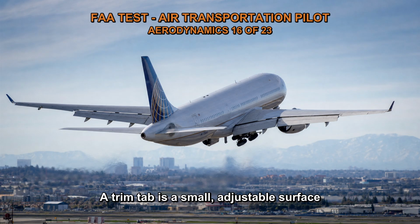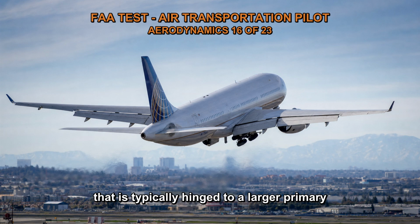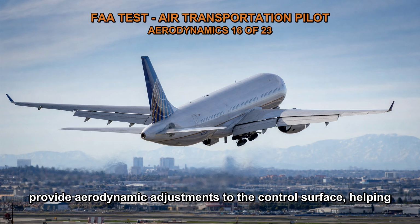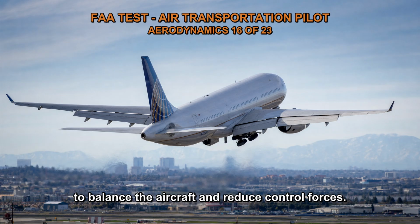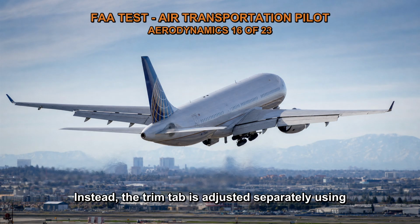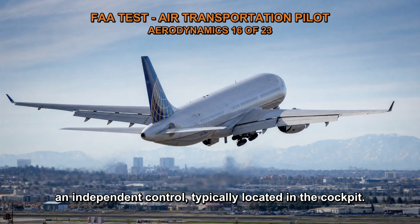A trim tab is a small, adjustable surface that is typically hinged to a larger primary control surface, such as an elevator. The purpose of the trim tab is to provide aerodynamic adjustments to the control surface, helping to balance the aircraft and reduce control forces. However, the trim tab itself does not move when the primary control surface is operated. Instead, the trim tab is adjusted separately using an independent control, typically located in the cockpit.